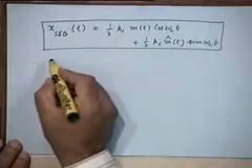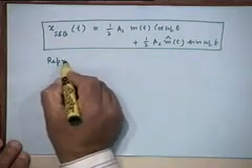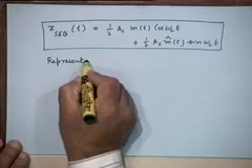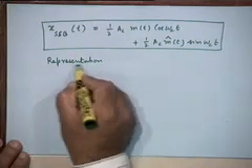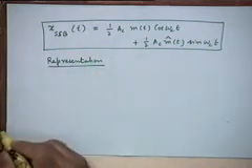But for an arbitrary waveform it is very difficult to see what the Hilbert transform will look like, right? So in general it's very difficult to visualize it, but for specific kinds of waveforms it may be easy to do so. Now this is the representation that I was talking about, the mathematical representation of SSB signals.